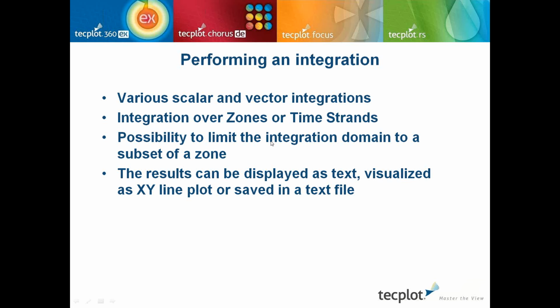You have the possibility to limit the integration domain to a subset of a zone. So if you want to integrate within a range of indexes, for example, you can. The result, you can display it as text on your frame or save it in a text file, but you can also visualize it and plot it as an XY line plot.